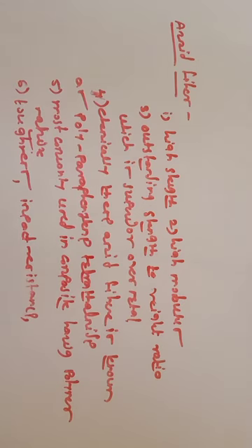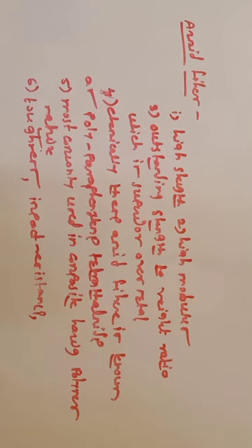Again, as compared to glass and carbon fibers, aramid fibers are susceptible to degradation by strong acids and bases. So this is the weak point regarding aramid fiber. No doubt they are very useful, but they are susceptible to degradation by strong acids and bases, though they are chemically inert to other solvents and chemicals. So this is all about the classification based on the reinforcing phase, and we are very much interested in the fiber reinforcing materials such as glass fiber, carbon fiber, and aramid fibers.